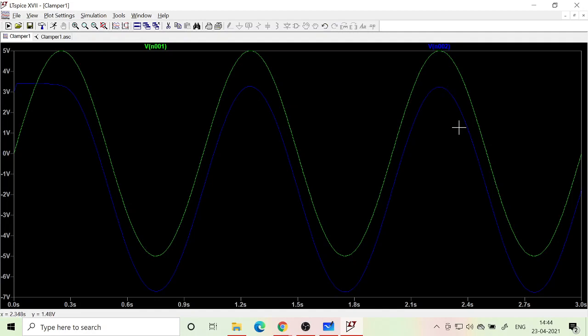You can see there is a transient here. This will only happen at the beginning, that's the transient period, but when you come into the steady state, it is a perfect oscillation. Sometimes it may take a few cycles, but here in one cycle everything is sorted out. Now the transient will also depend upon the capacitor value and so on, how long you need to wait. That depends on the component values, like in this case the capacitor value.